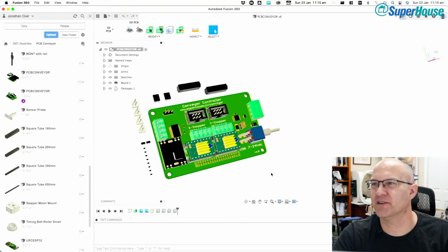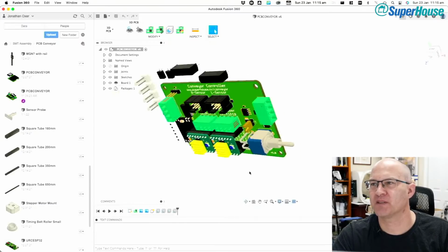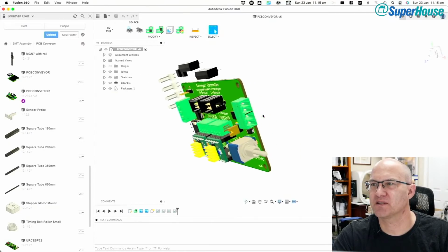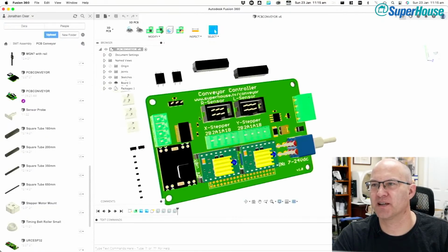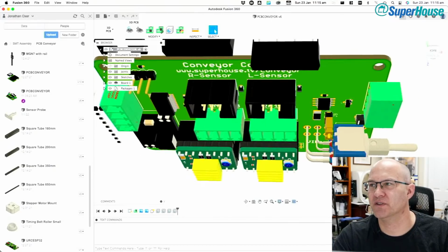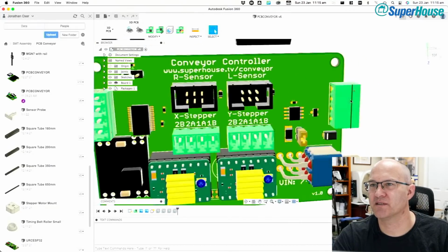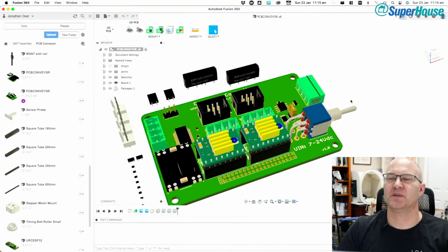Now, where are we? Oh yeah, that's right. So what I just did was I replaced the footprint. So for these pluggable terminal blocks, they can either come out the ends of the case, or I can have it come out the back of the case just by using vertical versus horizontal mount pluggable terminals. So that's also something that I'm going to be messing around with.